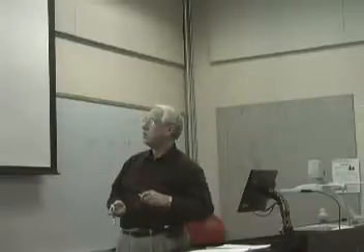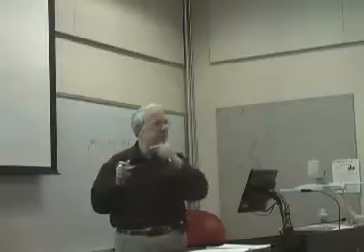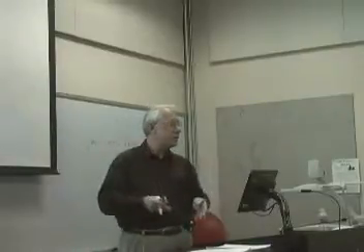So if I look at a 2D triangle, it's basically just a triangle with 3 nodes. This is a linear approximation. It's the simplest geometric structure that accommodates irregular surfaces, as I said. You have to remember that since you're doing this element by element, you have what are called the local node numbers, 1, 2, 3, and then you have global node numbers, because for every element there's 1, 2, 3, 1, 2, 3. But then you have to associate the local number with ultimately the global number in the whole computational mesh.